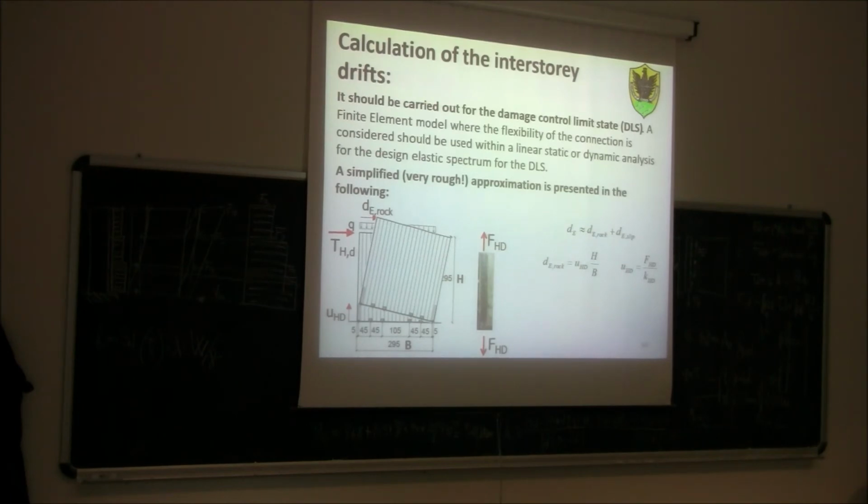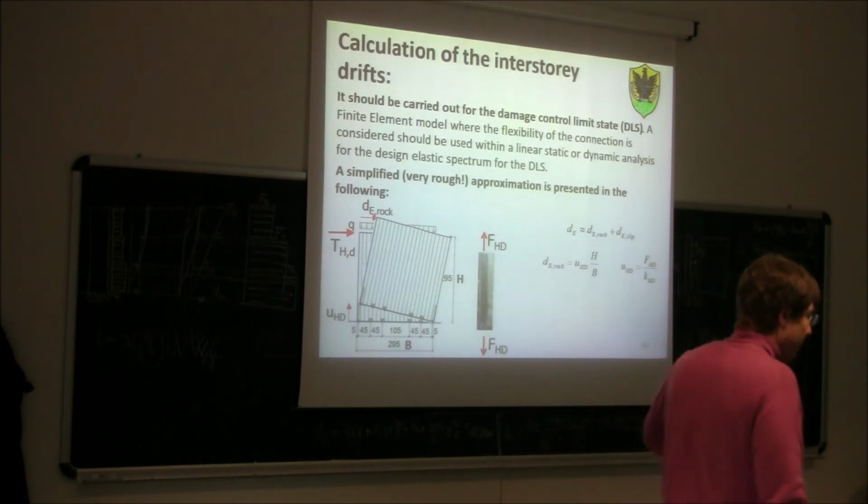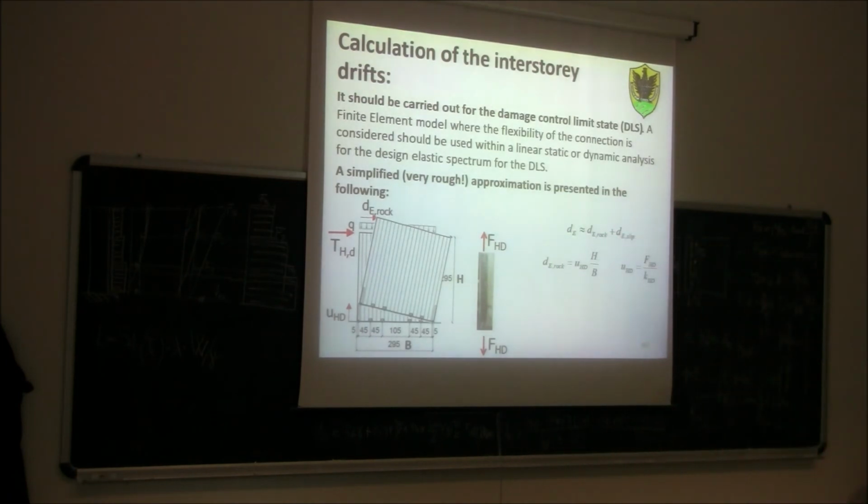That's basically not the plasticization, because I'm talking about damage control, it's the elastic deflection of the nail connection. So the elastic deflection of the nail connection can be calculated this way. UHD is FHD, the force acting in the hold-down, divided by the stiffness of the hold-down.